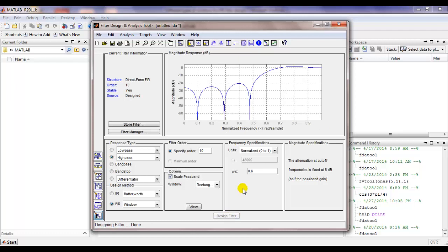This is what I get, right? We looked at it. Our cutoff is 0.6 pi. And if you look at it, you are going from 0 to this is your -20 dBs. It takes you about a distance of 0.2 pi. And the height, the maximum ripple size, is about -21 dBs. You can change the length as we did last time as much as you want. It's not going to affect the maximum ripple. The other ripples will go down, but the maximum ripple is not going to go down.